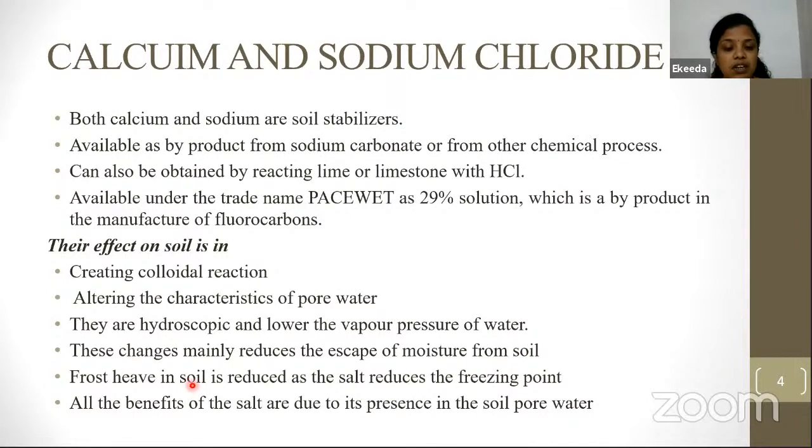These changes mainly reduce the moisture loss from the soil. The frost heave in soil is reduced, that is, the freezing of the water inside the voids gets reduced. And all the benefits of the salt are due to its presence in the soil water.